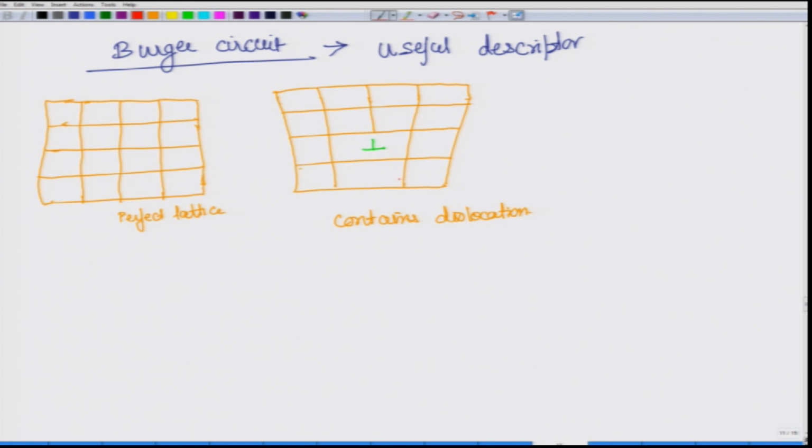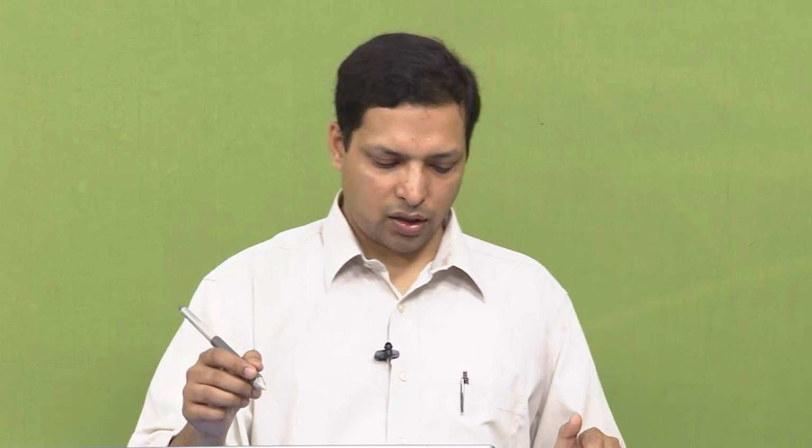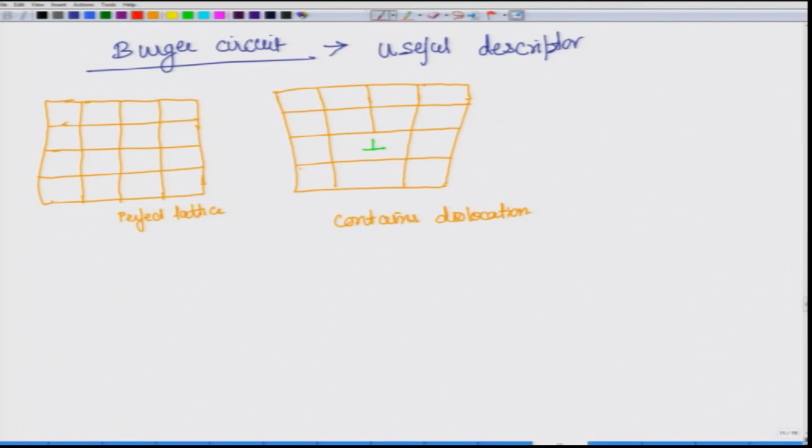region containing the dislocation will describe the Burger vector, and if there is a gap, the first thing is that it implies that there is actually a dislocation. So, let us see what I am trying to say here. Let us say we are going 1 in the right direction, 4 to the bottom, then again 3 to the left, and again 4 to the top, and since I had gone 3 to the left, I will come back over here, and we already have 3 over here.